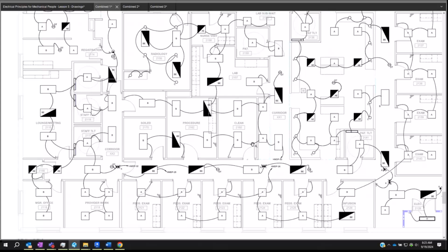So there are 2 design approaches. You can say, okay, manufacturer 1, I've designed around you. Manufacturer 2 is acceptable, but the contractor's got to give me a design to approve. Or you can do the most overall: of the 2 manufacturers, this piece of machinery requires at most 20 signals. So if one has fewer signals, well, great, we've just got a bunch of extra conductors installed, go for it. It's basically a worst case scenario design. When you don't have somebody specific in mind, it costs the client more. When you're designing to somebody specific, it is much cheaper and easier on the client, but it does cause other issues on the backside.